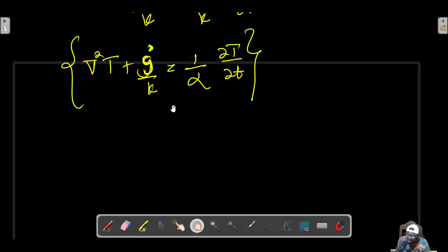But for this equation, the temperature depends on both spatial coordinates and time as well. There is heat generation within your material. That is one thing you need to know. Now, if you include the general assumptions we made, we said that there shouldn't be any bulk motion of the molecules or individual particles within the solid material.